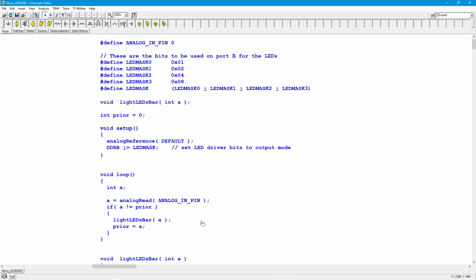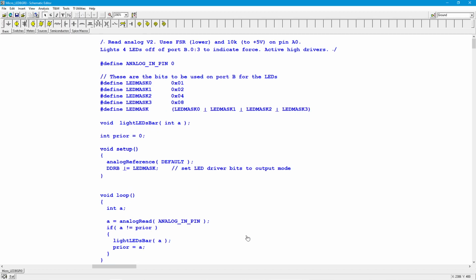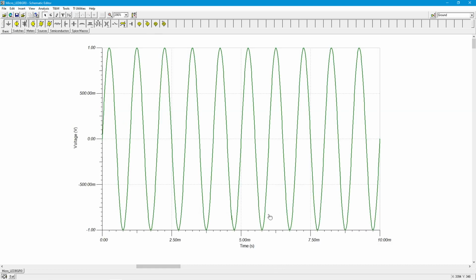Now, when you have this sort of time discrete or time discontinuous kind of process, this opens up the possibility of something called aliasing. So let's say we have a sine wave. This is my very simple input, right? I'm not going to use like a fancy audio signal. This is just a sine wave. So the comparators would be looking at this continuously, right? Always, always, always. And the instant we get a change, boom, the LED is going to light up because the comparator is going to flip.